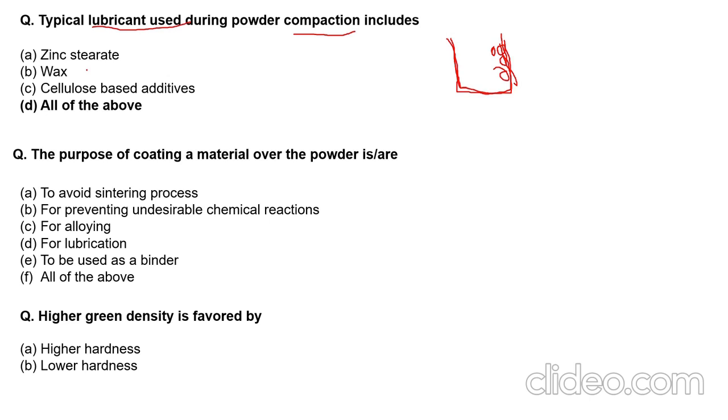Binders are also such as, like I told you, PVA. Then, depending on what kind of process you are doing, in processes like pellet making or iron making, there is one binder that is known as bentonite. Bentonite clay is used as a binder in iron making and pellet making. That is also one of the methods of compaction or pelletizing.